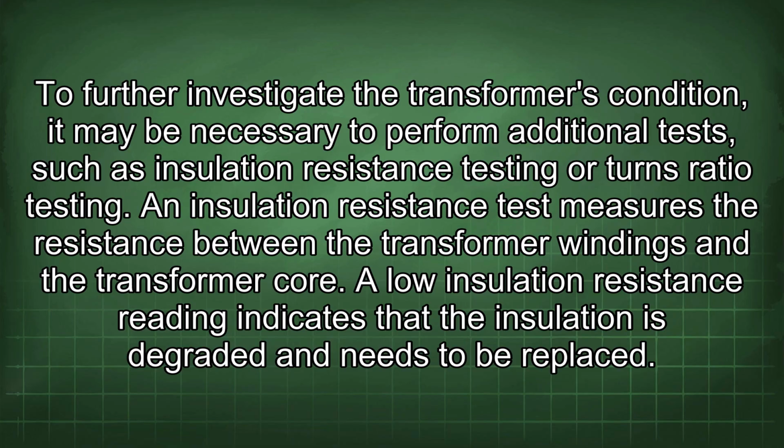To further investigate the transformer's condition, it may be necessary to perform additional tests, such as insulation resistance testing or turns ratio testing. An insulation resistance test measures the resistance between the transformer windings and the transformer core. A low insulation resistance reading indicates that the insulation is degraded and needs to be replaced.